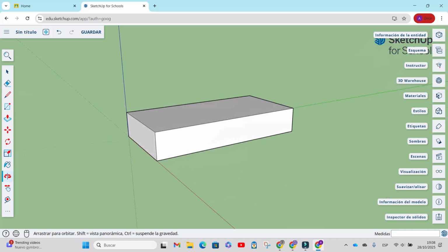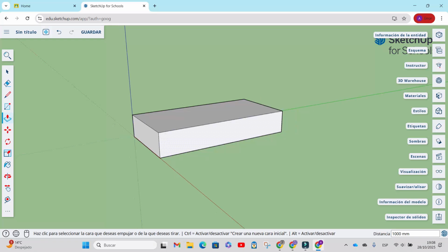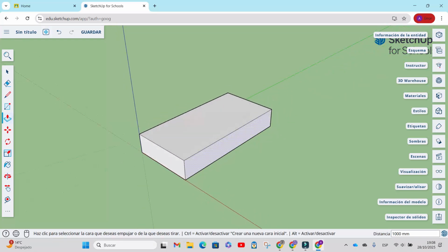this form. We are going to draw another rectangle on the XY plane. Choose here again this tool. Mind that when you click, you see the rectangle following you. If you press Ctrl now without clicking again, you see that the rectangle changes to be centered on the first point.